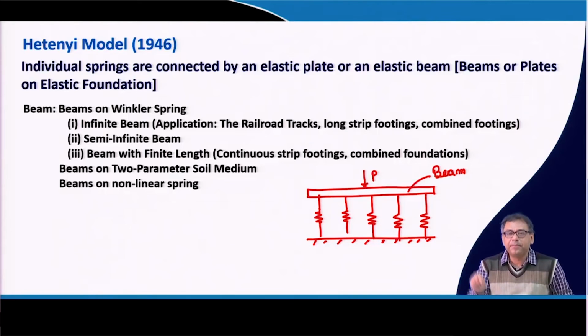Now again nonlinearity, time dependent effect, all this can be incorporated. Now the question is, as I mentioned, that settlement cannot be confined within the loaded region, but if this beam is resting on a spring only, then again this settlement will be confined within the loaded region. But if you want to get the settlement beyond the loaded region, which is the actual case, then you have to place this beam on a 2 parameter model. So, that means this is the beam on Winkler model or Winkler spring.